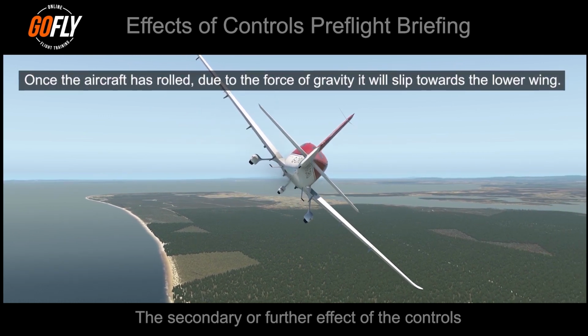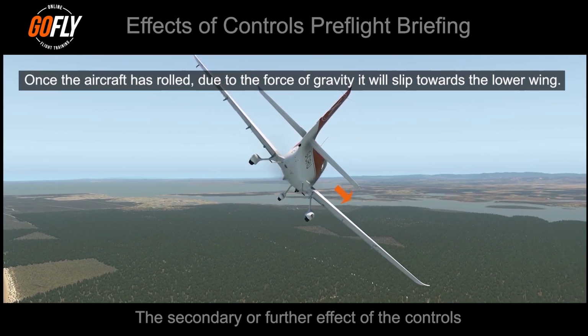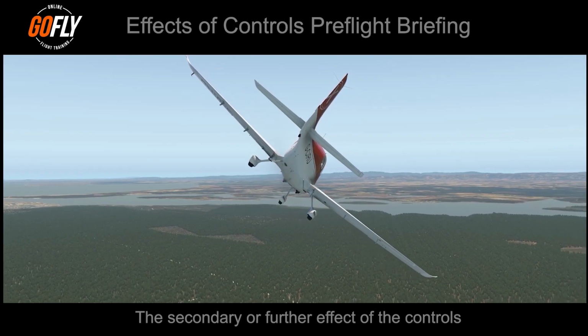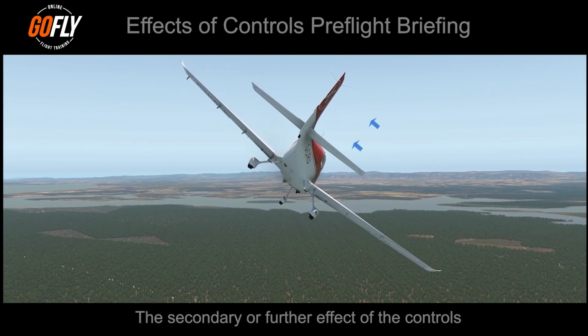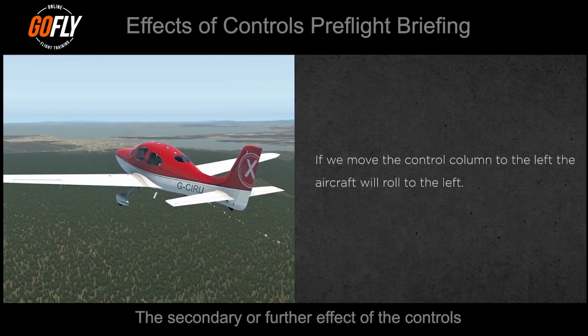Once the aircraft has rolled, due to the force of gravity, it will start to slip towards the lower wing. As the aircraft slips, the airflow increases rapidly against the side of the aircraft, and in particular the tail surface area of the aircraft, causing the aircraft to yaw in this direction as well.